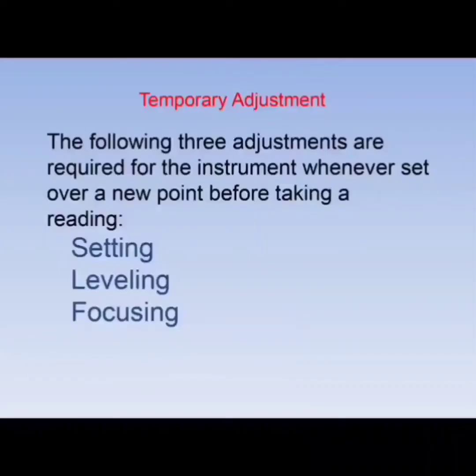Before taking levels, you have to make temporary adjustments to the leveling instrument. First, we have to set the tripod on the survey station, unbox the leveling instrument, and fix it over the tripod.